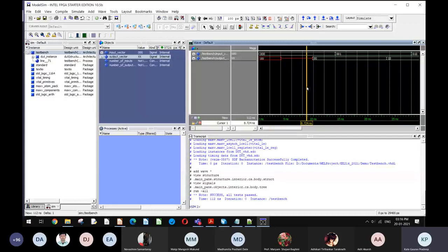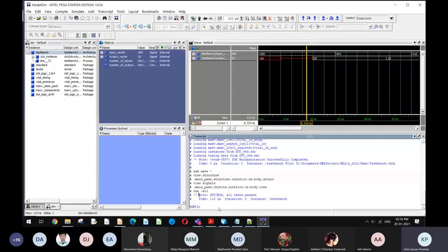So where can be the failure when we actually do the gate level is when, if you say you don't wait for long enough. Let's say, instead of waiting for 10 nanoseconds, I will wait just for 5 nanoseconds. So for doing this, I will go to my test bench and I will reduce that waiting time to 5 nanoseconds and check what happens.